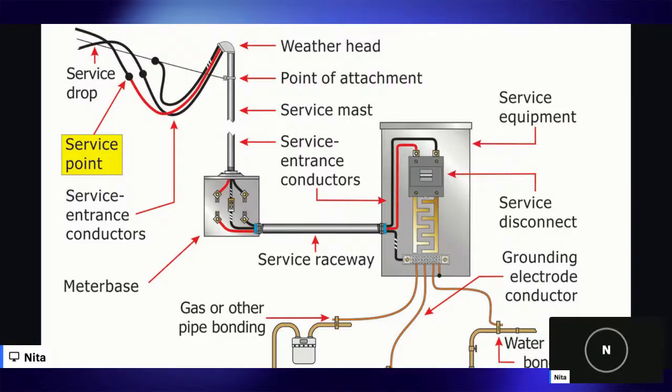And then you're going to have a drip loop. Hold up. So after my service point, my service drop conductors continue. Is that what you mean? Yes, they do continue. No, they became a service point. Yes, they became a service point. This right here is the service point. The service point is literally the splice.